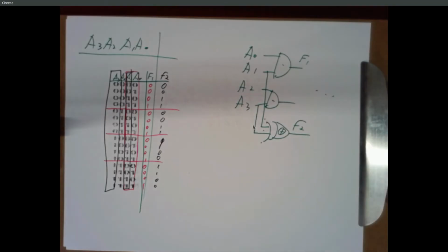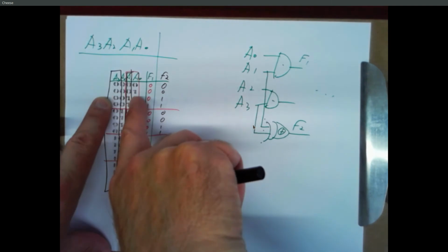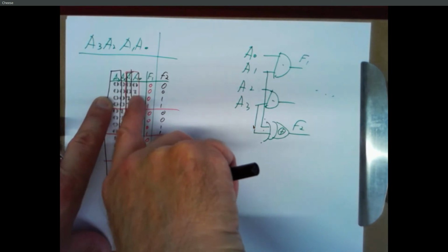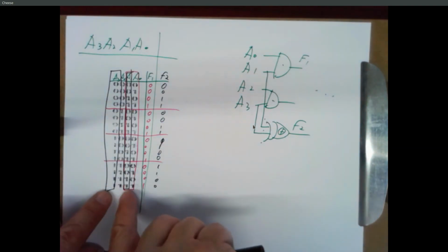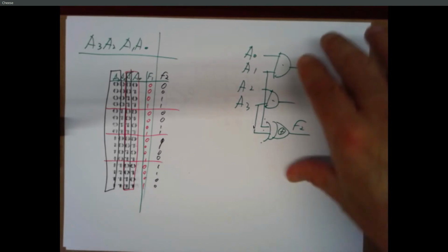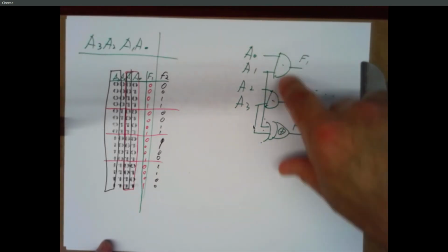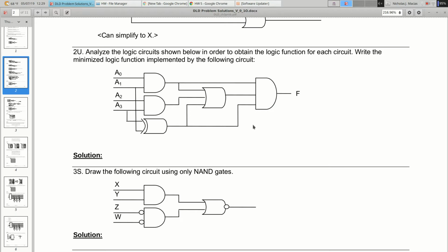There you go. So here I'm just looking at A1 and A3, and anytime exactly one is 1 and one is 0, my output's going to be a 1. If both inputs are 0 or both inputs are 1, the output's going to be a 0. And so to fill in the values for these intermediate points, I never have to do anything very complex. I'm doing simple operations of 2 things. But you can piece those together, right?